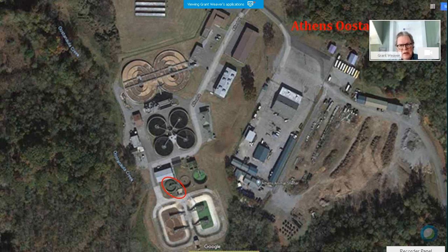They took a clarifier, they built a little pumping station beside it, they figured out an elevation in that old clarifier that was the perfect elevation that if they sent about 10% of their waste flow into there, it would sit for 2 to 7 days and ferment.